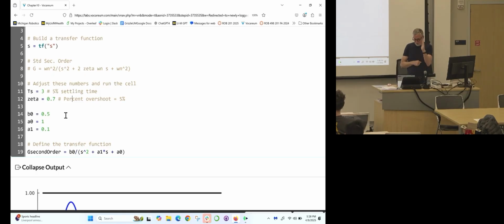Yeah, and then how much oscillation? Well, what you want is your analytical stuff on your mathematical design, when you put it on the model, to get you close, and then you can just tune a little bit by hand. You run an experiment, you change one knob, you run another experiment, you put it back because it got worse, and you go the other way. Okay, so you hand tune at the very end.